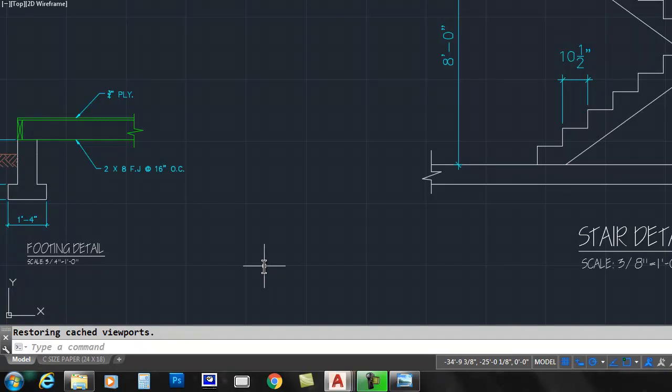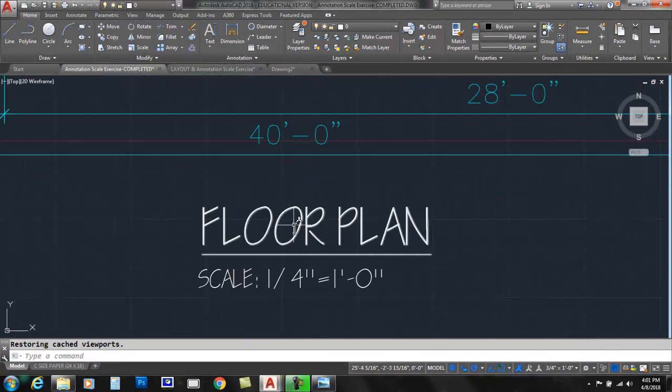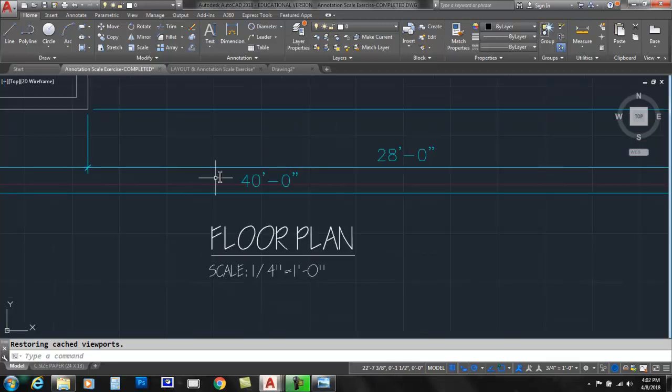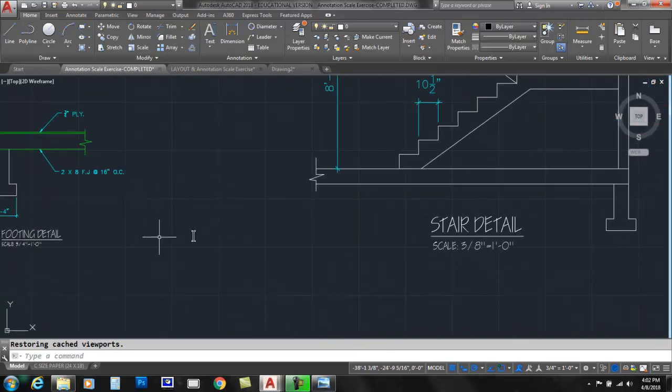if you were to do this manually, and we know from our Dimension Part 2 lesson, we would have to consult that chart. I refer to it as the cheat sheet. Or I would just simply do the math to figure out at that scale with a 1/4 inch text height. I believe this scale we talked about a lot. In order for this to print at a 1/4 inch, it has to be 12 inches tall in model space. In order for this to print at an 1/8 inch tall, it has to be 6 inches, right? And that's at a 1/4 inch to the foot. Those values would be different in each one of these 3 different scales.